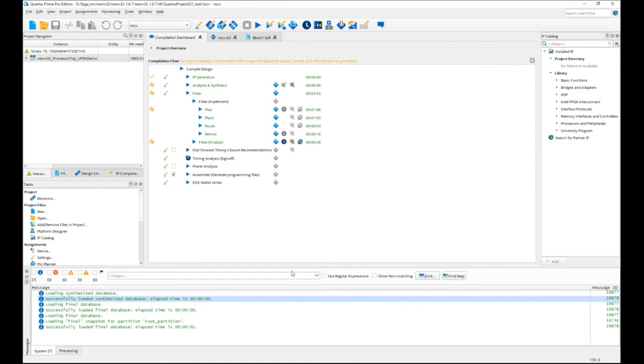There is a tool called DSP Builder, and what DSP Builder does is take the M code, the MATLAB code, and compile it to, I think, VHDL. Then from there, Quartus will take the VHDL files and run them through. So it's kind of like high-level synthesis, but dealing with the MATLAB code.